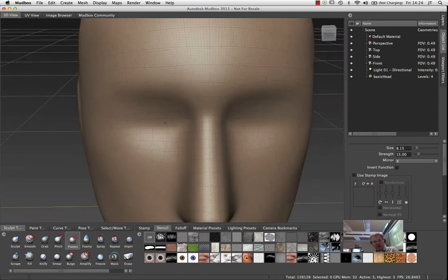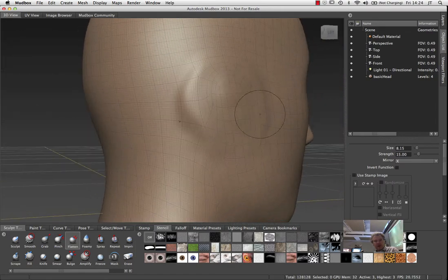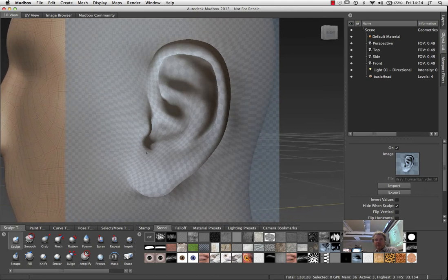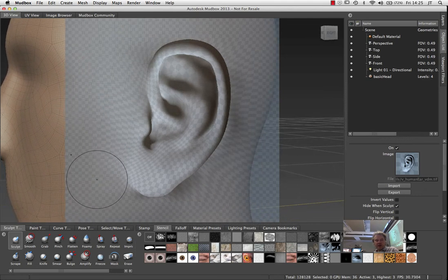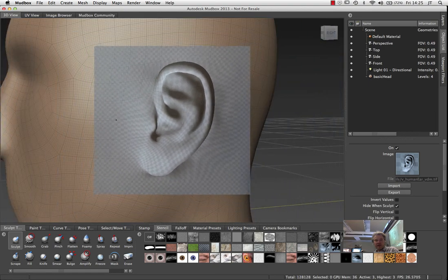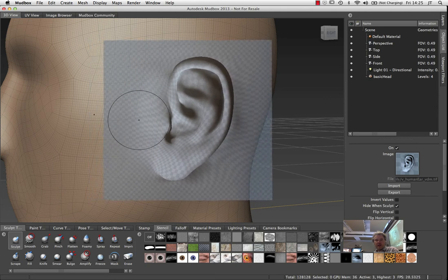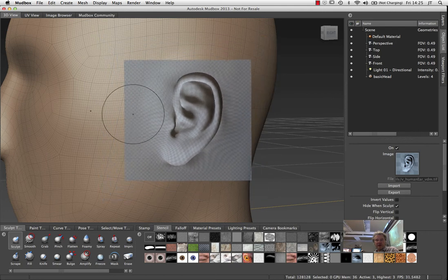But if I look at the profile now, the ear part has much more of a chance to start from normal. And then I'll go back to my Sculpt tool because that's actually giving the shape. And again, I've got a very high strength on this. And I'm going to select the ear. This is where I actually have to turn it back around. Now, as well as adjusting the object you're sculpting, you can also adjust this template. If I hold down S on the keyboard and use the right mouse button, I can scale that up and down. Similarly, the middle mouse button will move it along, and the left one will rotate it slightly. So you've got options of working it in a couple of different ways there.